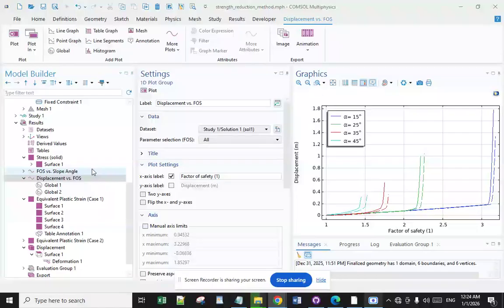Landslides predominantly arise from two aspects. One is external force, which could break the initial stress equilibrium of the geological body and may cause slope collapse or sliding. The other is a change in geological properties that causes the shear strength of the geological body to decrease. A slip disaster can have substantial consequences such as the blockage of roadways, the interruption of traffic flow, and structural collapse. However, there is no uniform standard for judging slope stability.